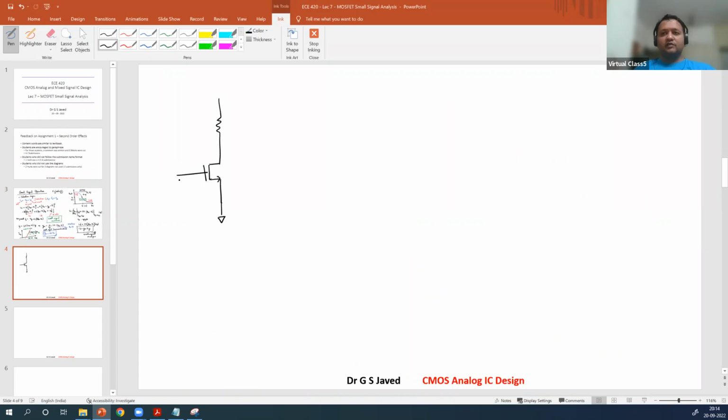This is the equation that we used, and in this case, we will apply two different voltages. This is capital V, capital G, a DC voltage. And this is a small AC voltage, small v GS. This is applied at the input, and this value, with reference to the ground, is given as small v, capital GS, indicating both DC and AC components.